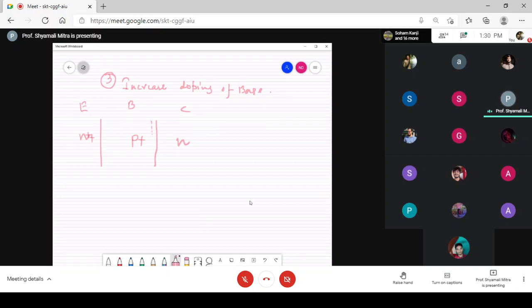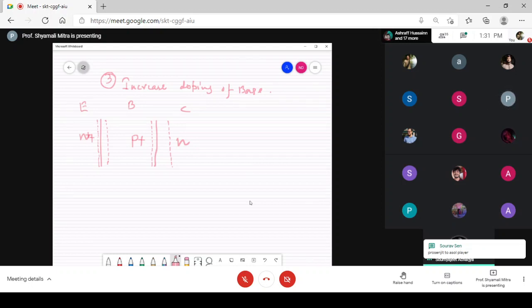more and more depletion region will extend towards what? Towards the low doped region in this side compared to P plus. So in this case, what happens? This will have larger depletion width compared to this side. So if I want to shrink the depletion region on both the sides with the same ratio, what should we do? We increase the doping concentration by an equal amount.